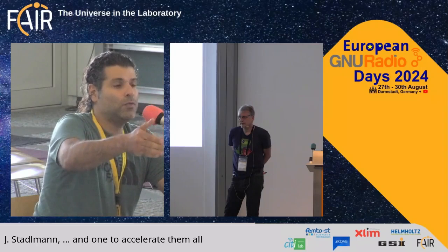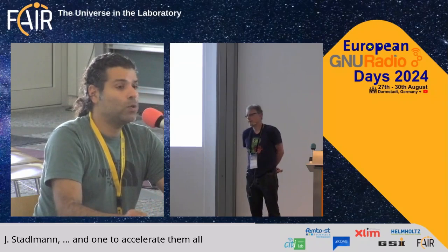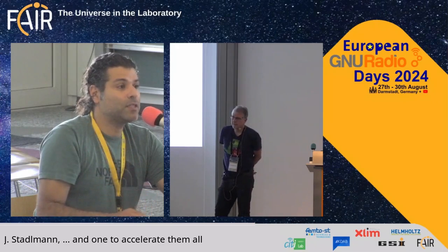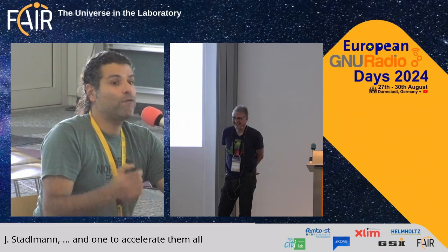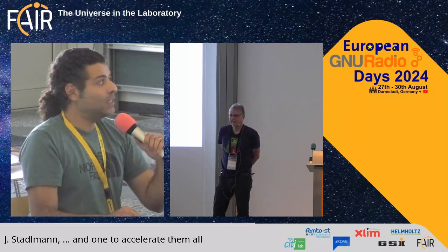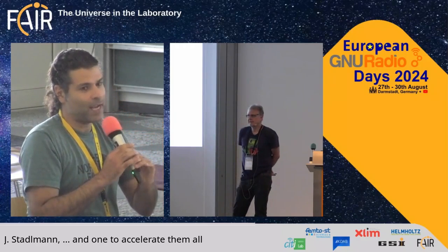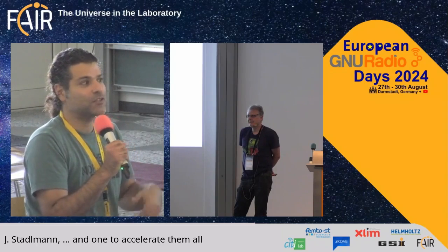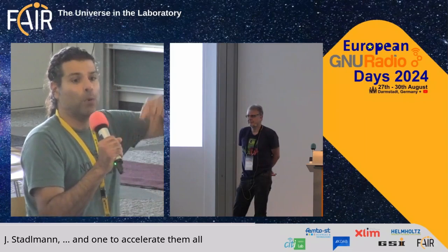Or if you want to use it for tumor therapy, the location of the beam has to be known. Or you just want to measure the revolution frequency, or the beam intensity. So there is a huge amount of different information that you can get from these RF detectors, because they are non-destructive. They are really just kind of antennas around it. I really hate the name antennas, because they are not really antennas. You can consider them as a secondary loop of a transformer whose primary loop is the particle beam itself.